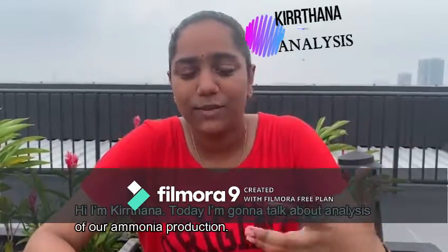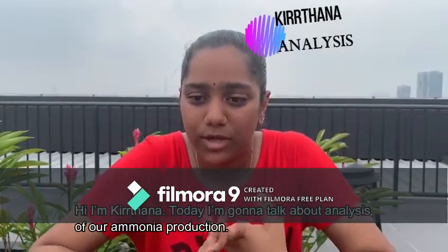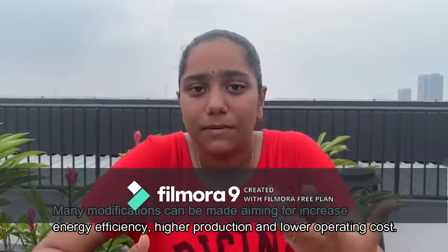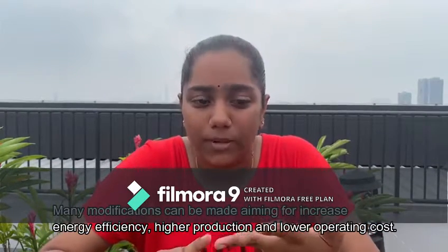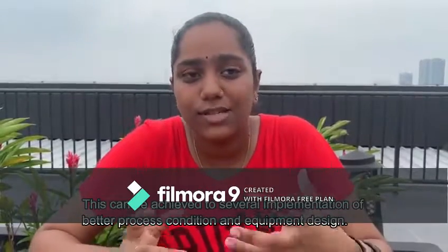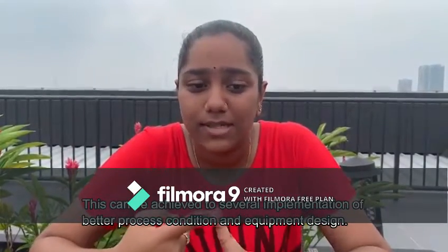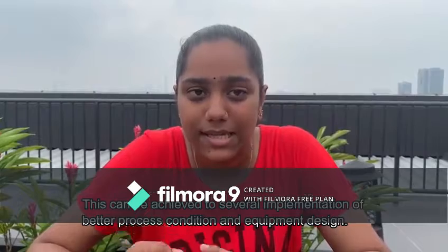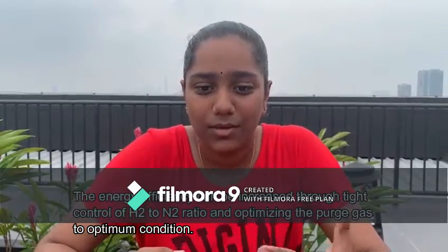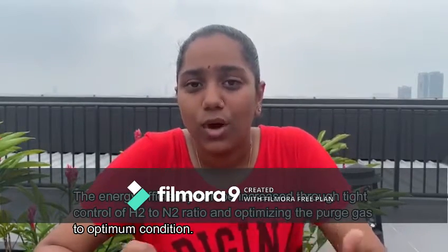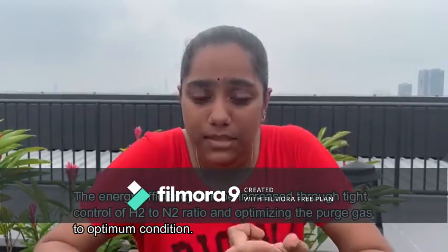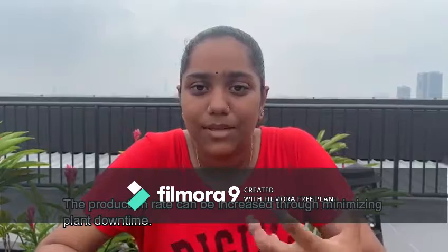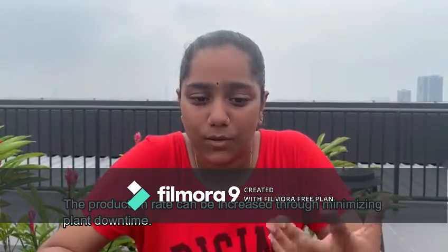Hi, I'm Kitana. Today I'm going to talk about analysis of our ammonia production. Many modifications can be made aiming for increased energy efficiency, higher production and lower operating costs. These can be achieved through several implementations of better process conditions and equipment design. The energy efficiency can be increased through tight control of H2 to N2 ratio and optimizing the purge gas to optimum conditions. The production rate can be increased through minimizing plant downtimes.